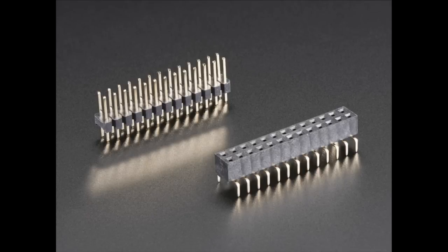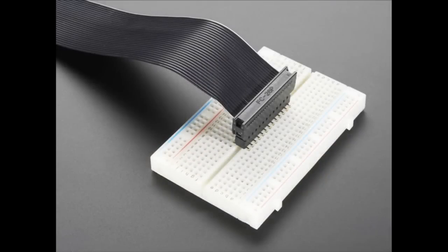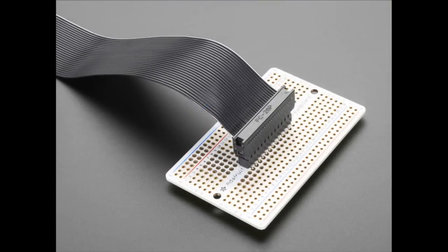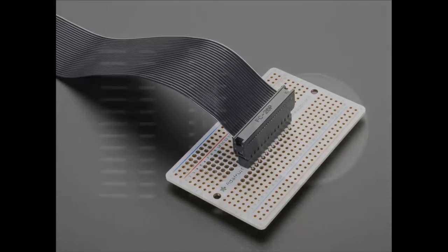It's actually 2 pieces that I'm kind of abusing. And then what you can do is plug into a breadboard and you just plug in the IDC cable on top and you basically have a breadboard friendly IDC connector and you don't have to solder anything. Also works great with, of course, Perma-Proto or any other breadboard system that expects 0.3 inch split chips, which is the most common size chip, so pretty much any kind of breadboard.